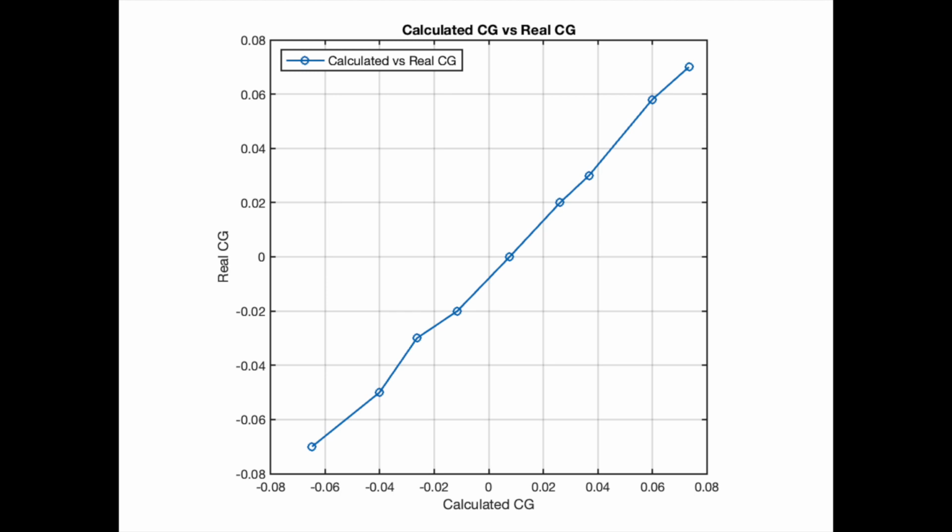Plotting the measured CG against the initial test CG should ideally result in a line passing through the origin. Any discrepancies from this line are not significant. Understanding the nose and tail tipping points is crucial for determining safe CG positions. Exceeding a longitudinal CG of 0.2 causes the aircraft to tip backward, while a value of -4 leads to nose-down tipping. Thus, staying within these CG limits ensures the Albatros remains stable.